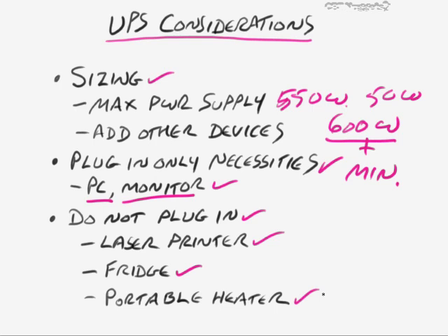But as you can imagine, those portable heaters draw an immense amount of electricity, and so you wouldn't want that plugged into your UPS either. Otherwise, the few minutes that you'll get out of this, I think I can usually get about 15 minutes out of my 1200 watt one, that'll probably drain down to just a couple of minutes if it can even handle the additional power that's required from one of these appliances. You wouldn't plug a hair dryer into it or something like that either. And all of these things I'm telling you about, as far as what you plug in and what you don't plug in, I would be very well aware of this type of thing for A+, because it's definitely within the line of the exam objectives.